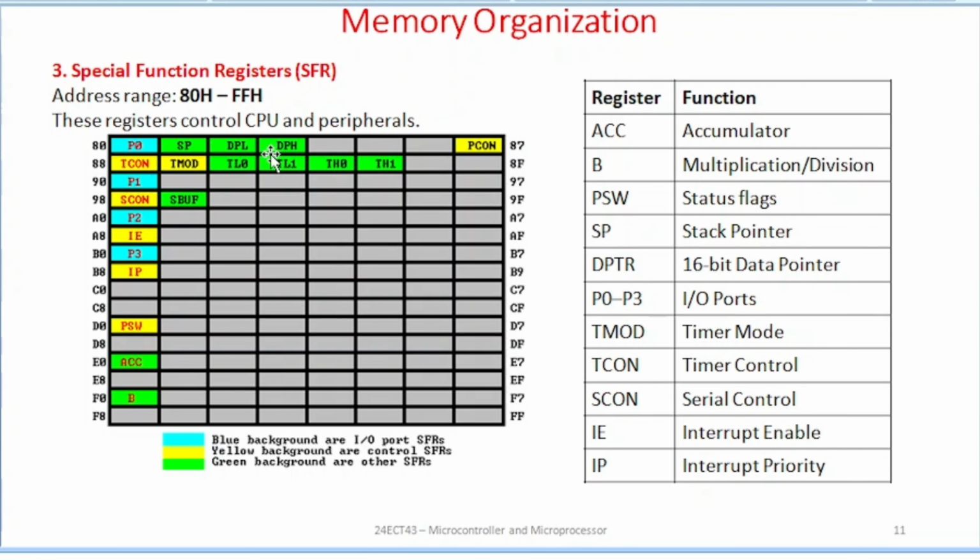When the program flow begins executing a subroutine, the stack portion may be placed anywhere in the on-chip RAM, but normally the stack pointer is initialized to 07 after a device reset and grows up from location 08H. The stack pointer is automatically incremented or decremented for all operations using push or pop instructions and for all subroutine calls and returns.